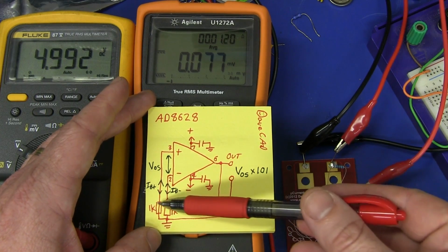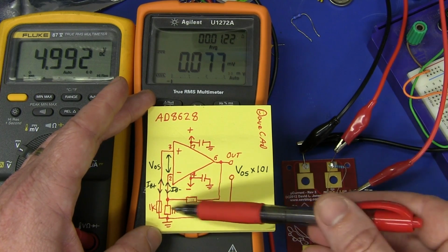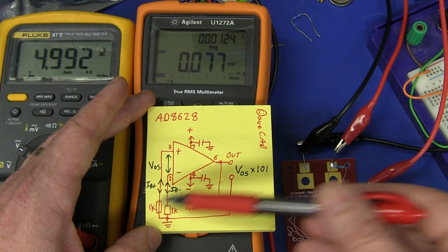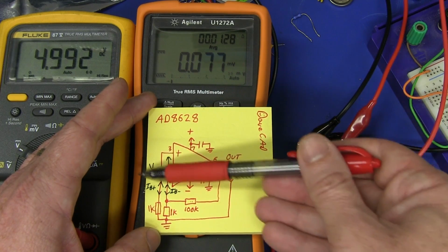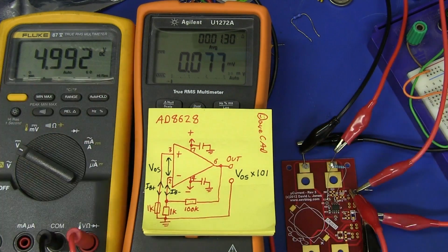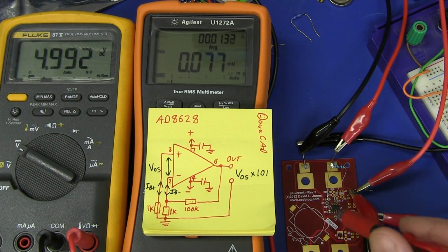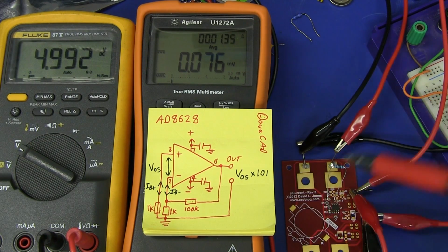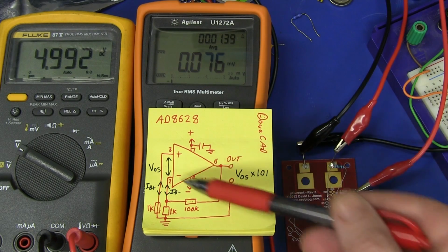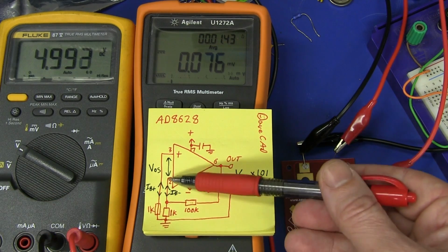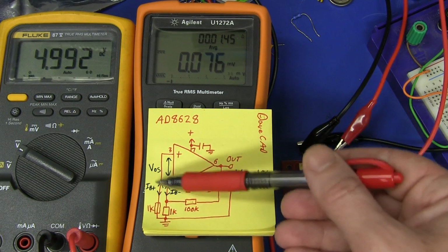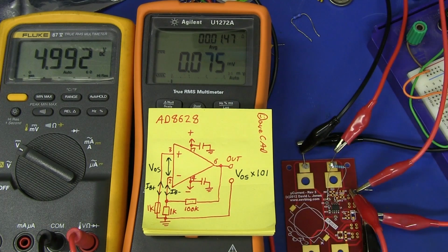So we've tweaked it by lowering these values and adding in our proper bias resistor. And we can probably say now that VOS dominates, but does it? We don't know, because we've only got one sample of this chip. I'd have to do like 10 samples to get meaningful data to see what the exact culprit is. We don't know whether the input bias is flowing in or out of either of those pins. It's just crazy.